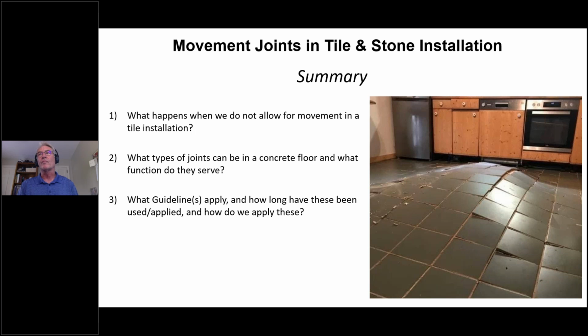So this question comes up sometimes about exteriors where they're recommending a 1/4 inch width. Gauge porcelain tile does not look the best with 1/4 inch width joints everywhere if you decide that you're going to put it up with nothing but sealant. But it could be the minimum thickness, whether it's 3/8 or whatever, or 1/4 inch in the movement joint, and then have a tighter joint throughout the field. But that just generally doesn't look the greatest. So they do not have to, though. I agree. They tend to look a little bit better, but they do not have to.